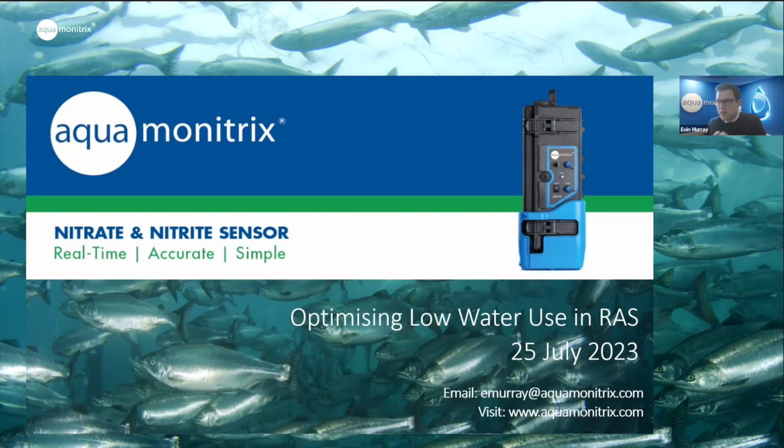Yeah, that's a good point, Mike. We touched on it briefly there in terms of the selectivity. Because we have our anion exchange separation within the system, in combination with our specific wavelength LED, it's highly selective for nitrite and nitrate. Similar to the salinity question, the fact that we have the separation up front, in combination with the matrix elimination technique that we use for sodium, with the sodium chloride mobile phase, we maintain high levels of selectivity for nitrite and nitrate despite increasing organic matter.